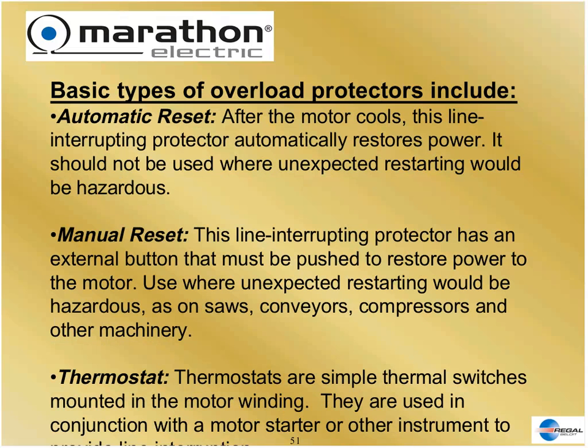First one is what's called an automatic reset. It has a thermal disc in it. That's the silver thing, if I can get it turned right, and this light. And it has terminals on the back to hook the line leads to. These things are both temperature and current sensitive. All right? So if there were an overcurrent situation or an overheat situation, this thing would snap open, similar to our other device that snapped open, and take the motor off the line and not cause a fire.